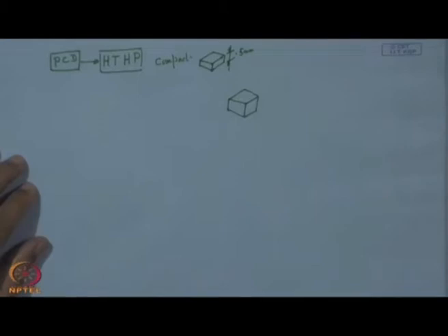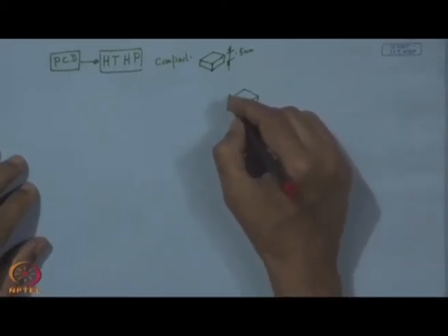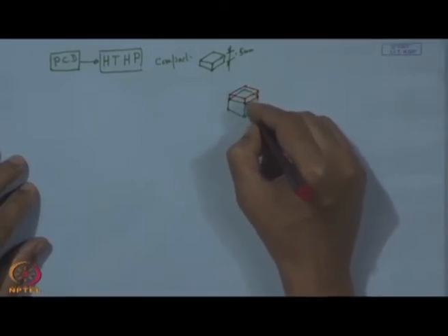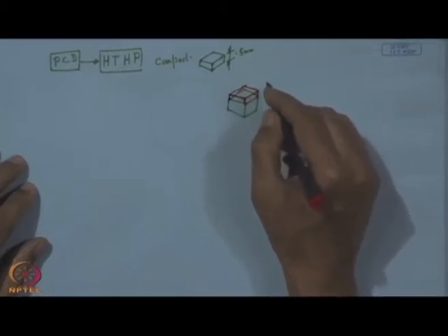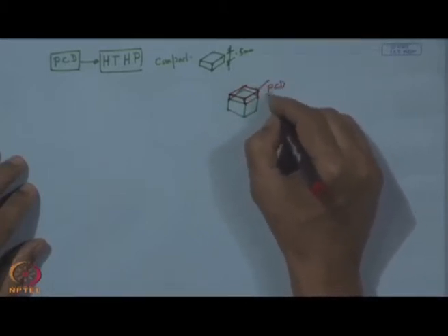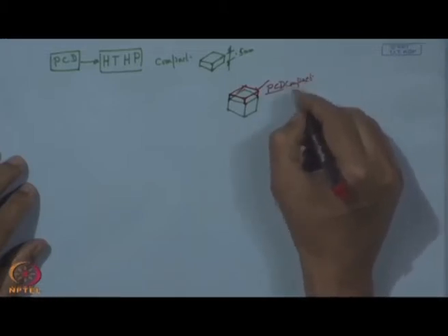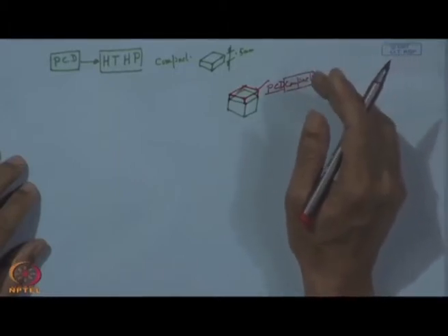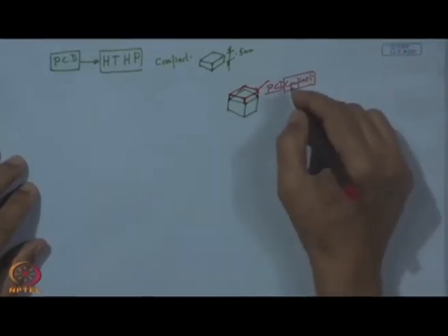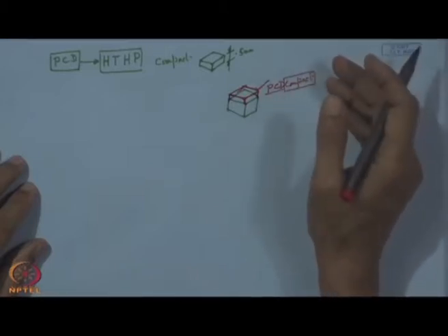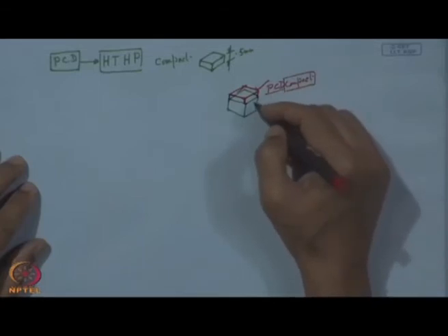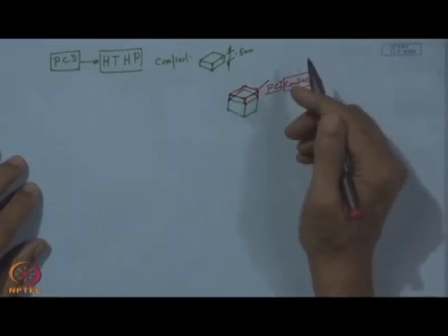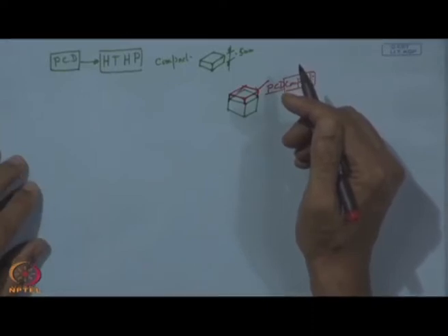On this is brazed. So, this is actually the tool. So, this is called polycrystalline diamond, the PCD compact. Now, the greatest advantage of this PCD over natural diamond is that it has multidirectional crystallographic orientation. So, the average toughness of this compact is greater than that of natural crystal, and this can be used for various heavy cut machining, where we expect high cutting force and the machining task is a little more difficult.